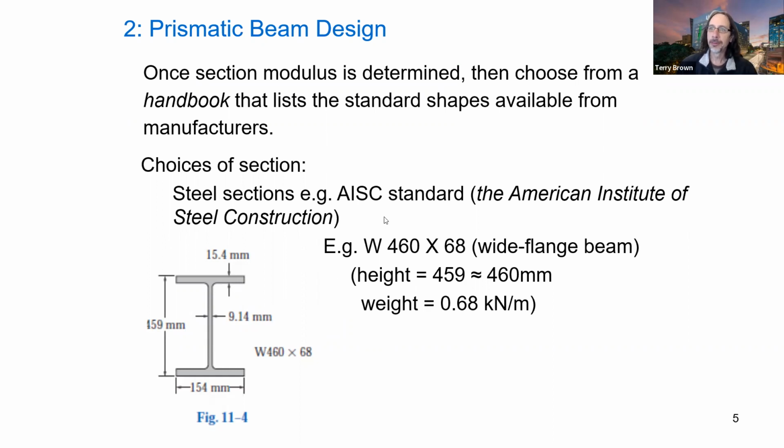Okay, so here we've got the American Institute of Steel Construction standard, and we have a wide flange beam. As you probably know, from general knowledge or from intro to mech, an I-beam is quite commonly used in beam construction and in structural design in general, because they're weight efficient. We have the stresses all being carried through the flange here.